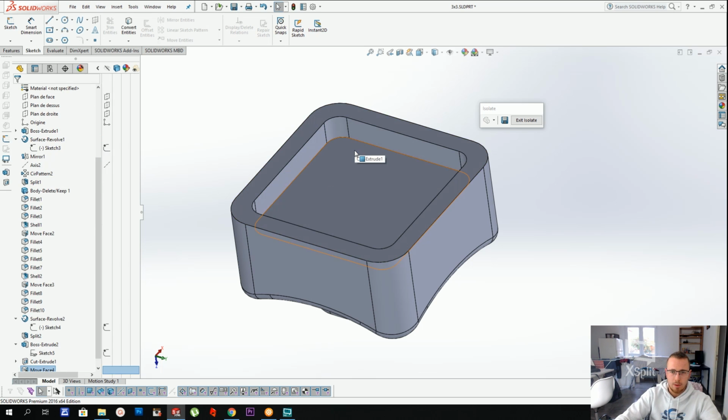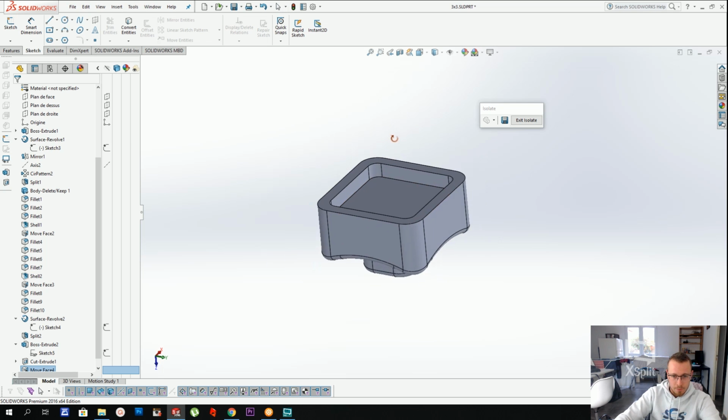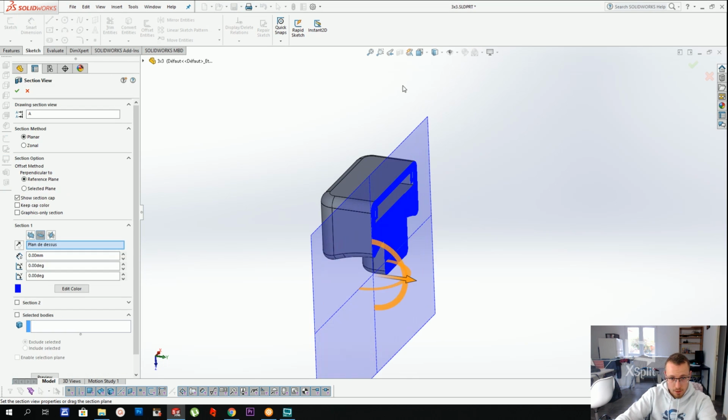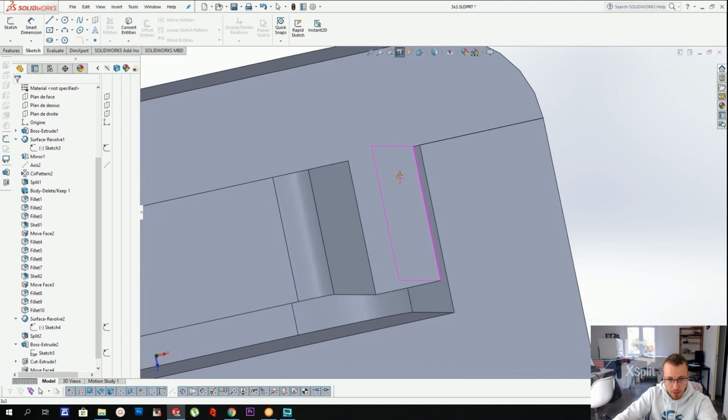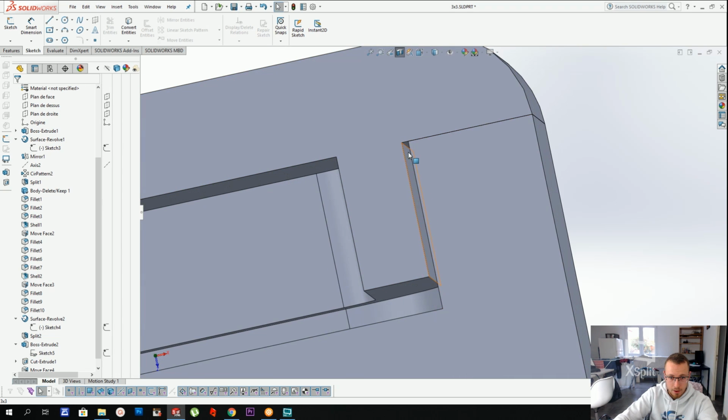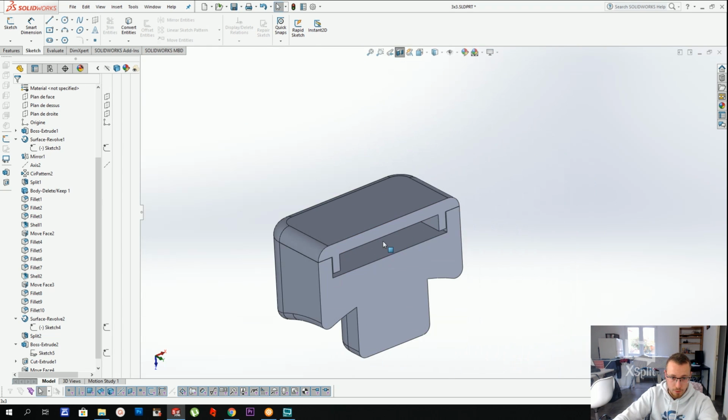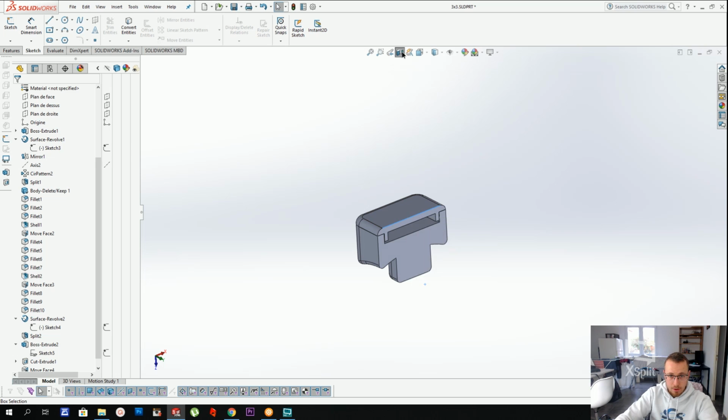0.2 is too loose, in my opinion, and 0 is just way too tight. You can't even push it in. So now, as you can see, there's a little bit of leeway to insert the cap right there. And that is wonderful. Alright, now that you've done this, the cap and its interface are complete.